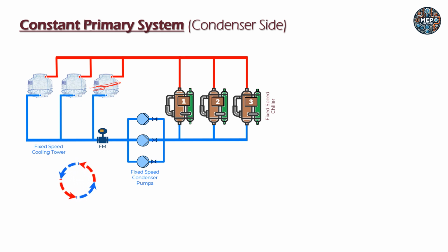The pumps here are designed to take care of the head loss across this complete pipeline, and the head loss across various valves and fittings, the chiller condenser coils, and the cooling tower nozzles. On the flow, how do we calculate the flow for these pumps? The required flow data is to be provided by the chiller manufacturer, or you can consider 2.5 to 3 GPM per ton of cooling capacity as a thumb rule to get the condenser water flow.